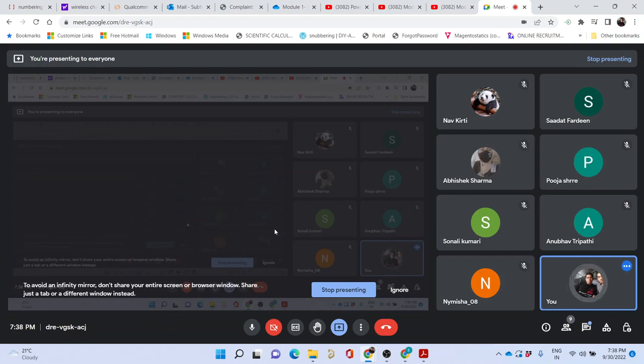So one thing that you have to keep in mind is that whenever we add a zero on the left hand side of the S plane, like the zero that I have just added, it has an effect of pulling the root locus towards the left hand side. It makes the system much more stable. Okay, this is one key takeaway point.